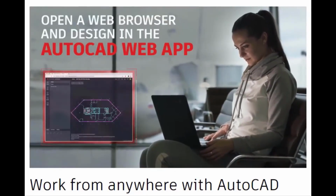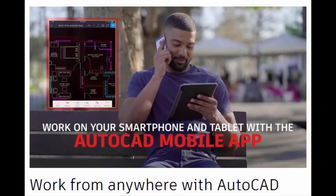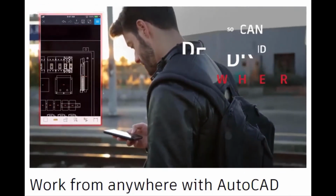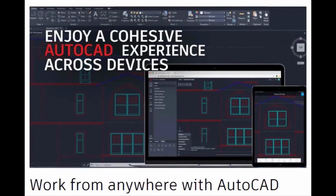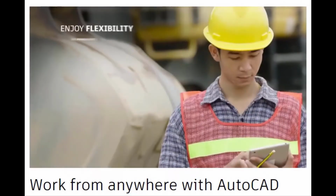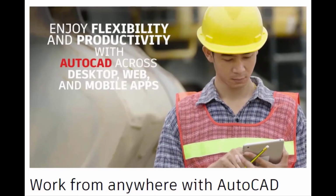Use the Save to Web and mobile feature to save drawings from your desktop to view and edit on your AutoCAD web and mobile apps. XREFs included. Easily go from drafting on your desktop to drafting on the AutoCAD web and mobile apps, and vice versa. And a bonus tip, you can open DWG files directly in the AutoCAD web and mobile apps with Autodesk's Cloud, as well as with Microsoft OneDrive, Box and Dropbox.